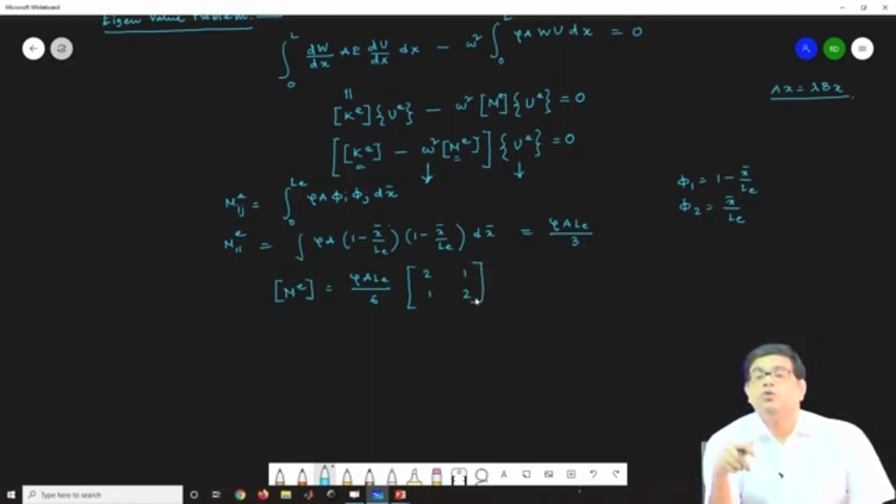Sometimes we use nodal lumping of the mass, that is, in the case of a 2-node element, half of the mass is lumped on one node and half on the other node. This leads to a diagonal mass matrix. Sometimes we also prefer the diagonal mass matrix when we simulate a dynamics problem or transient problem, which involves a time domain solution.